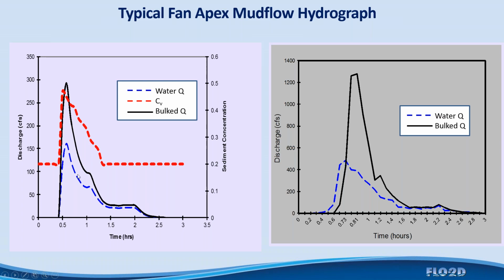And if you have some sediment that's approaching a typical mud flow, where the concentrations are on the order of 45 to 50% concentration by volume, these typically occur on the rising limb of the water hydrograph, and then the recessional limb becomes more dilute. This is if you have a hydrologic event occurring. So in this case, we have this concentration by volume, and it gives rise to the mud flow event,